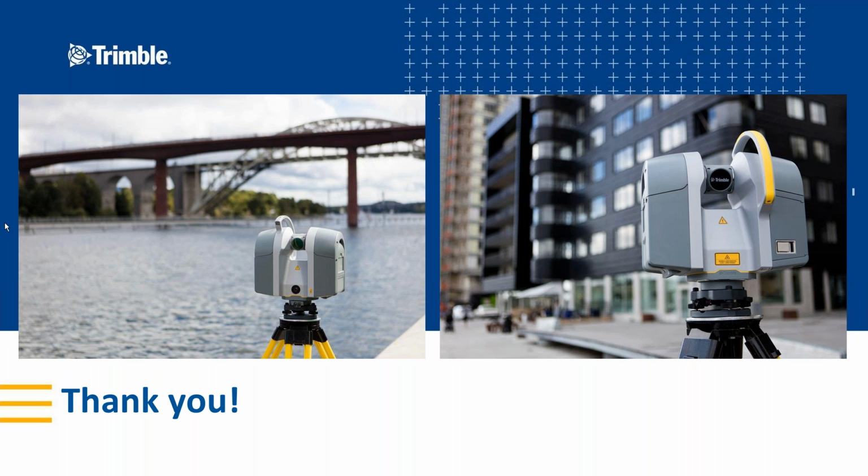Can you please explain the advantage of target ghosting? I wouldn't say that there's an advantage to using ghosting. It's more of an emergency type of application if you did not have enough targets in your possession at the time that you're trying to scan something. Maybe you didn't get all of the targets that arrived at site, and so you're limited with the number of targets that you have.